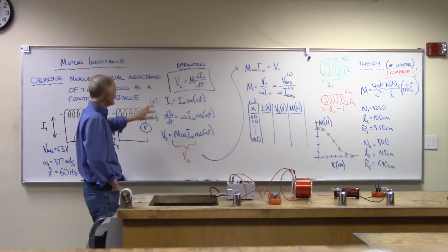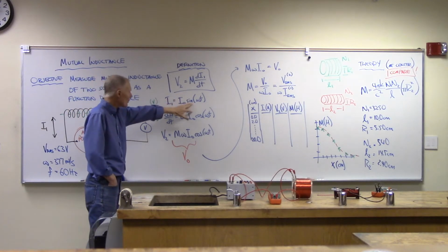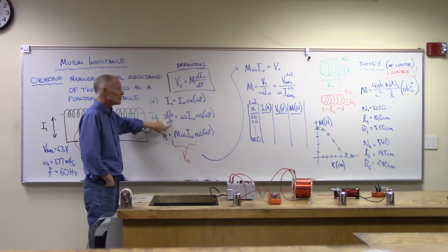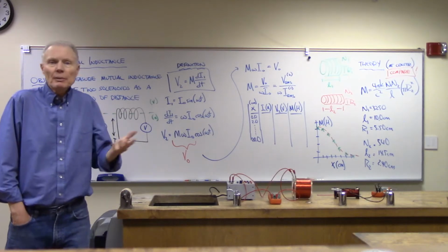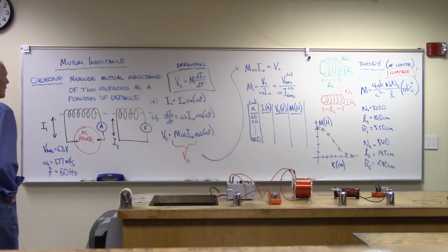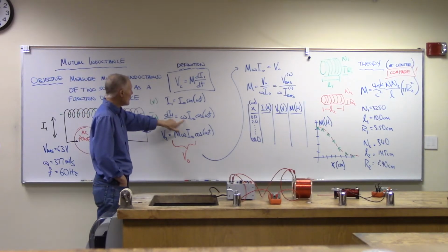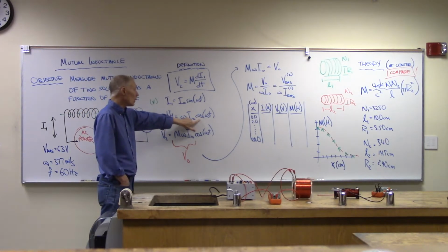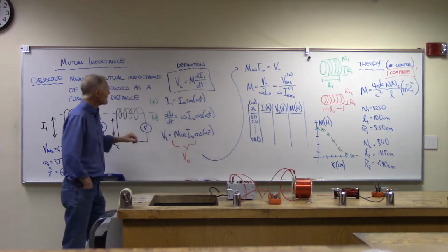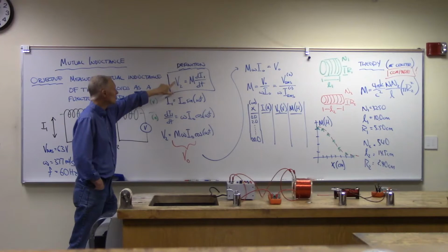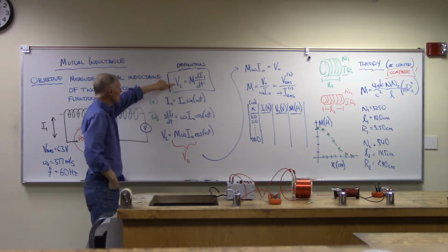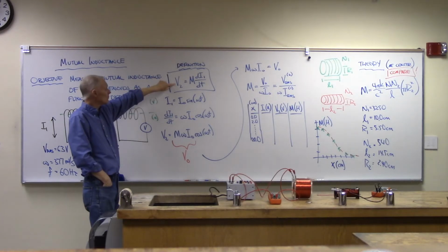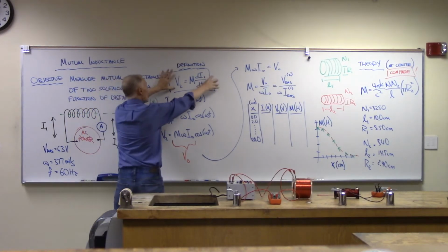Sine seems fine. Now, if that's what the current is varying like, what we're actually interested in is what is dI/dt. What's the rate at which the current is varying? And we just take one time derivative to come up with that value. So that's going to become omega times I naught times the cosine of omega t. Now what that tells me is this voltage, remember the current over here is varying like a sine function, but the derivative is varying like a cosine. That means the voltage here is varying like a cosine. Now what I'm going to do is I'm going to copy this formula over.